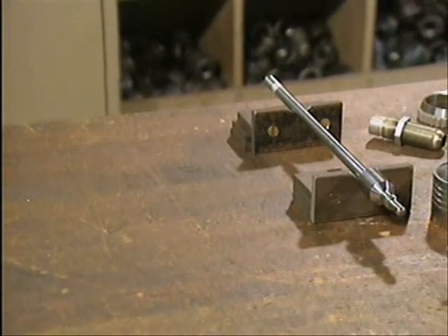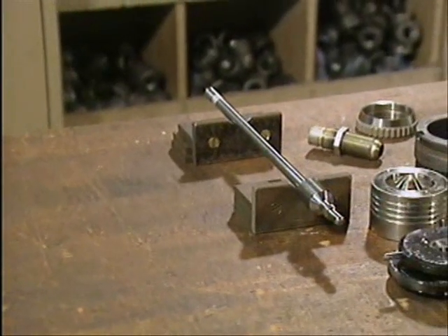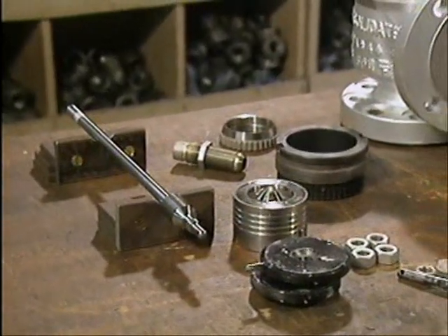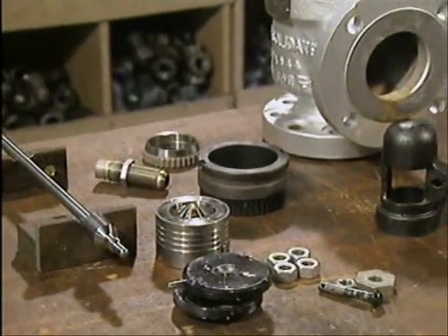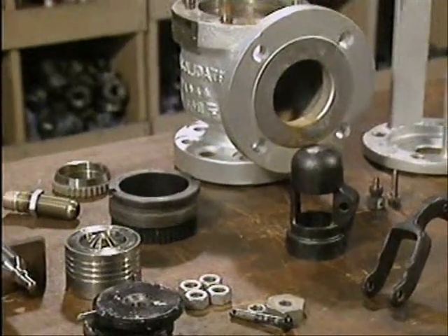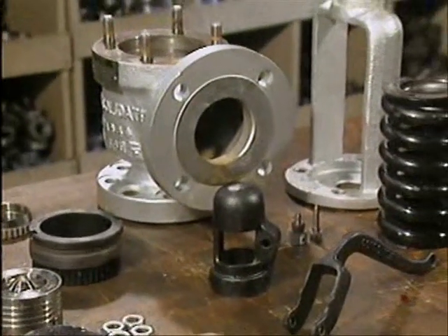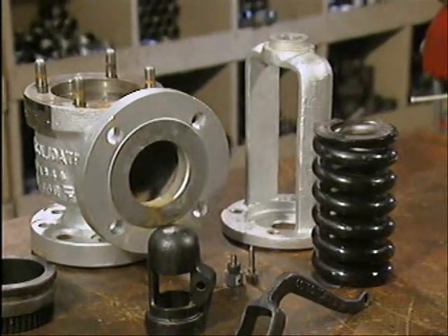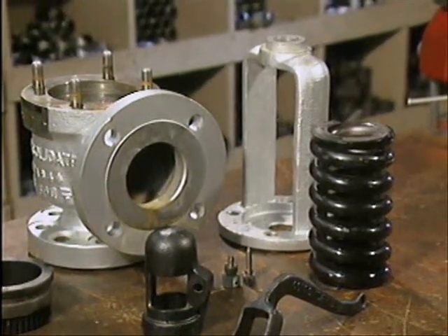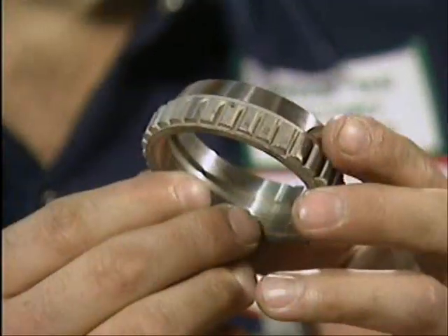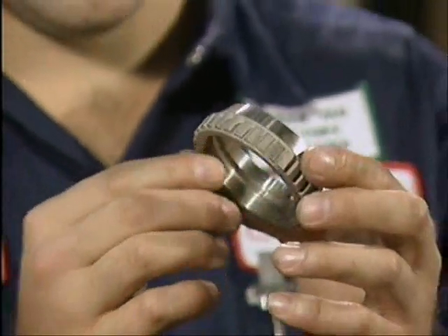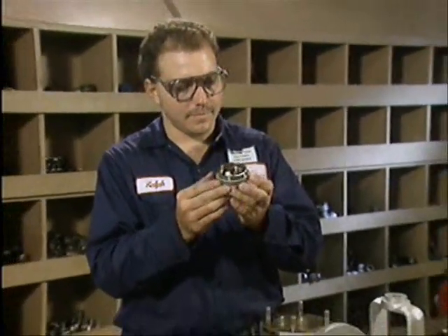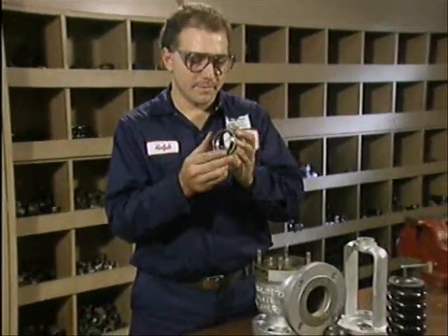After a safety valve has been disassembled and its internal components have been inspected, the valve must be properly reassembled and tested before it's returned to service. The valve reassembly procedure is basically the reverse of the disassembly procedure, but there are a few tasks specifically associated with reassembly that you should be aware of. One of the first steps in safety valve reassembly is making sure that you have all the correct replacement parts and that the parts are in perfect condition.